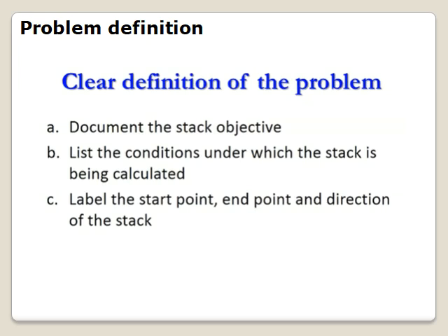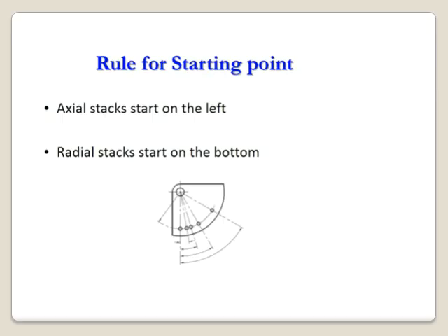Problem definition: clear definition of the problem. Document the stack objective, list the conditions under which the stack is being calculated, label the start point, end point, and direction of the stack. Rule for starting point: axial stack starts on the left, radial stack starts on the bottom.